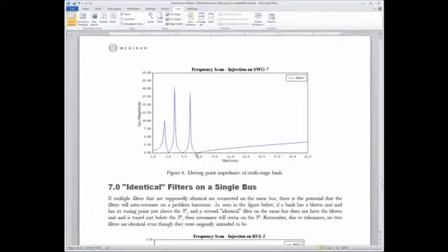You can see that this doesn't necessarily go all the way down to zero impedance here. The smaller you break this up into pieces, making 3, 5, 7, 11, and 13, you could break this up a bunch if you wanted to, you'll find that you're not going to filter as effectively each one of those harmonics.